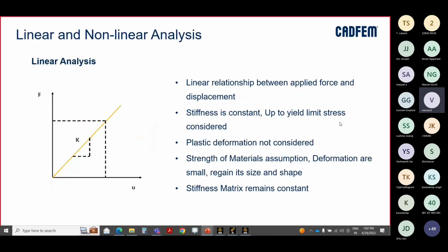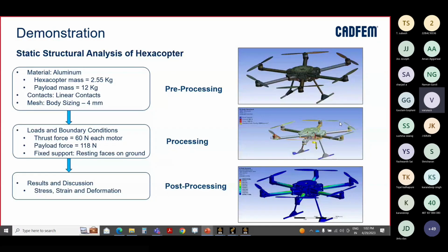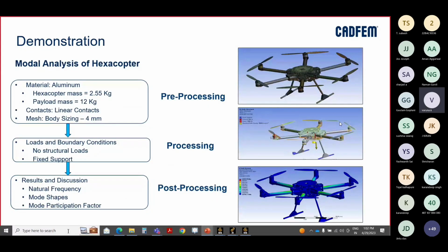Modal analysis comes under free vibration. There will be no external load. Here no structural loads, only fixed support will be there. Then we can do the modal analysis. We can check what the natural frequencies, mode shapes and mode participation factor are. On the same setup I will be doing that one.